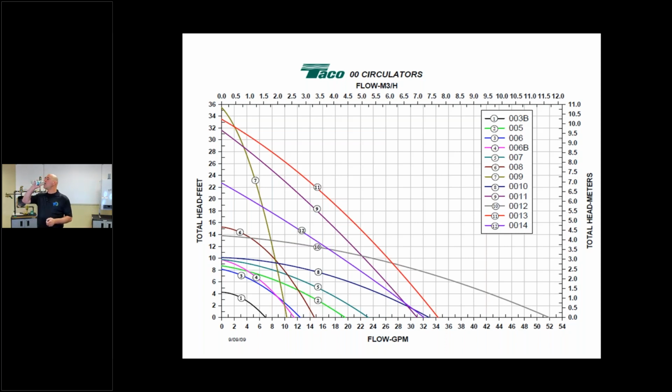In general, let's say he's got a 16-unit apartment building, and there's twin boilers in there, and there's 16 Taco 571s. His question was, how is this working? So my response to him was, well, what's the net of the boilers? What size circulators are there? Really, we should ask him how it's piped and everything like that. What size piping? And this speaks to the fact that hydronic heating is the most forgiving heat medium that anyone will work with. If that was a hot air system, forget about it, right? He'd be under duct sized or whatever.